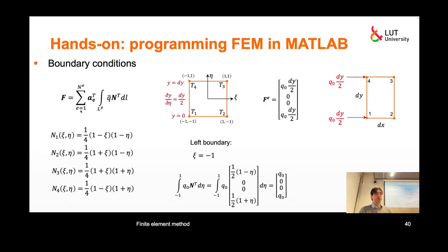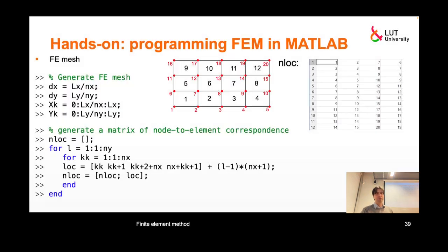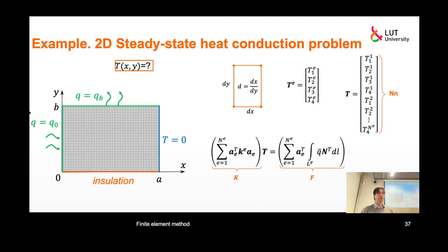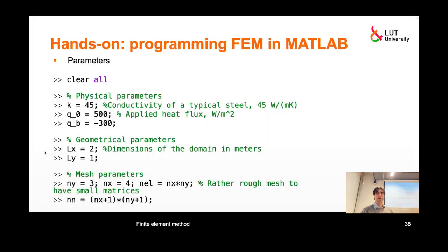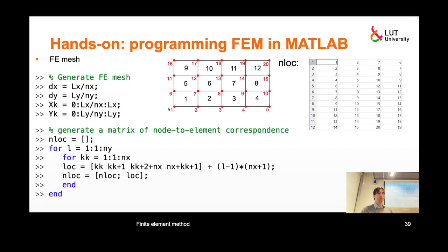I actually need to calculate those integrals. Of course, in the general case you would do that numerically, and for a general purpose code, you will have to write a general numerical procedure for that. But in our case, I want to make things as simple as possible to just solve this particular problem. Let's see what is in our case. In our case, we have heat flux. Let's start from this one on the left boundary. With respect to our mesh, this is the left boundary, right? So I will have to specify something related to those nodes.